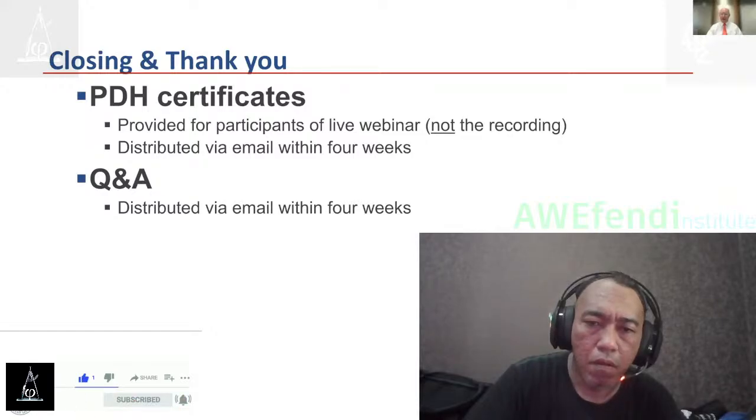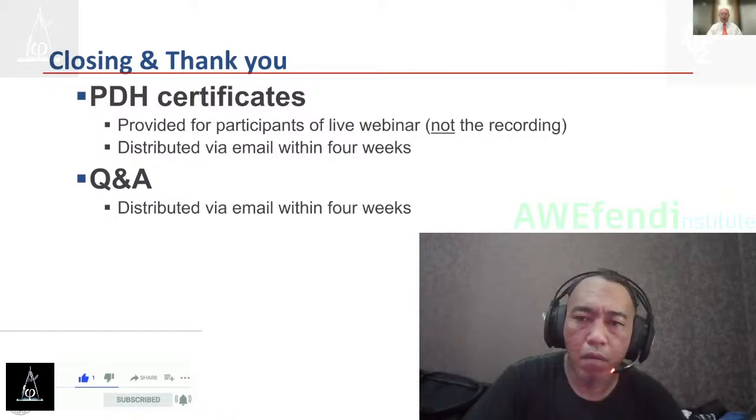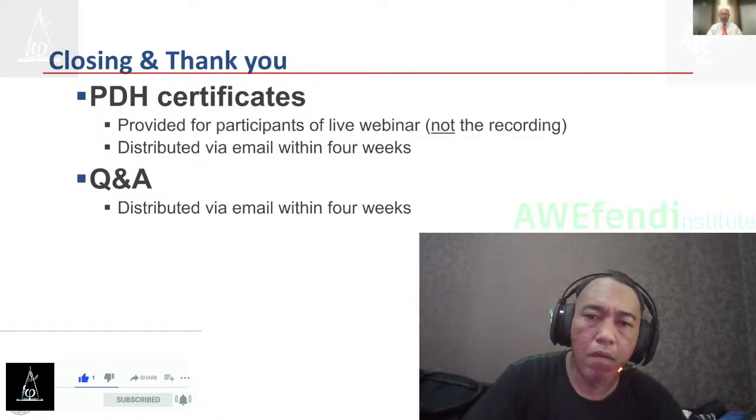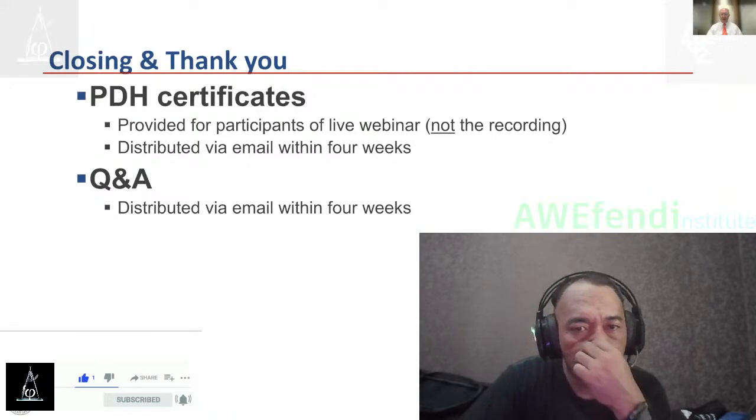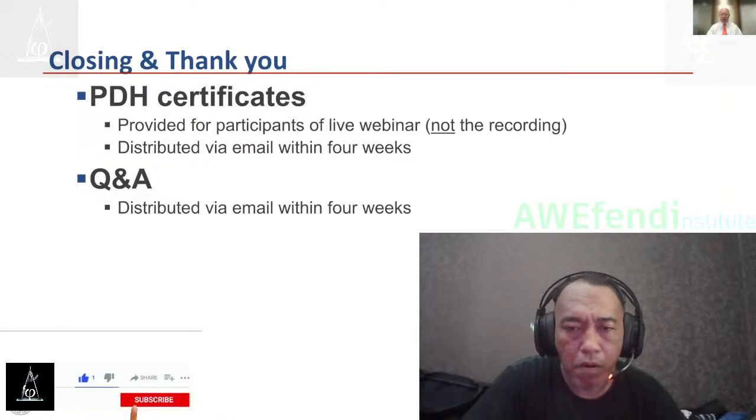Is the twist important or does it cause damage? That's a different question. I would say where this really comes into play is in ASCE 7-16 and earlier editions. There were times that having the torsional irregularity, the system was prohibited if the TIR was too great. And the problem with that is that if you have a system that only has 1/4 of an inch of displacement in a story, but the average is 1/8, that rotation is triggering a torsional irregularity, and the system is not permitted at all. And so the prohibition on the system was eliminated in ASCE 7-22.